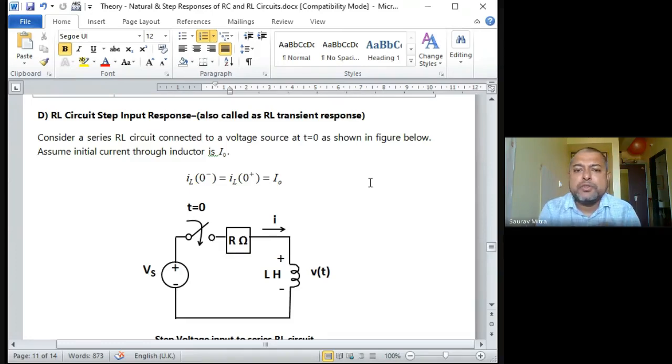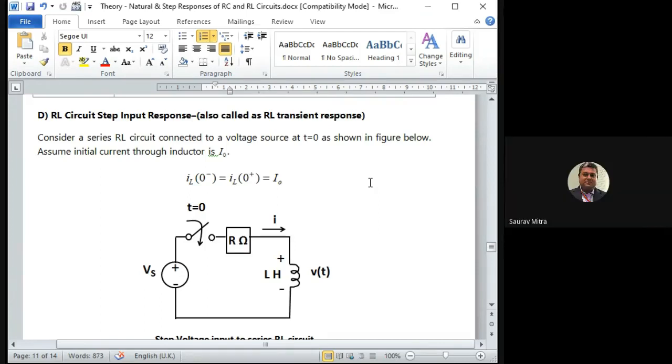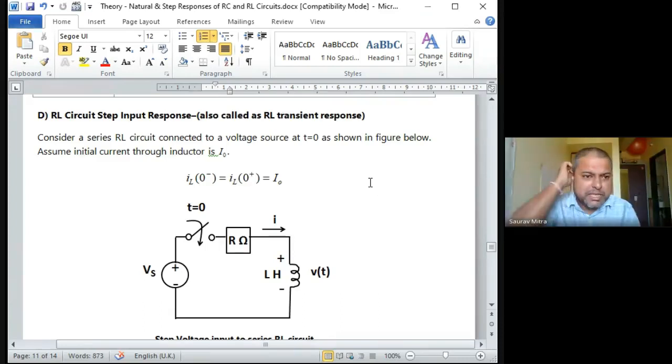So what is the conclusion we can draw from that last part of the experiment in experiment 2? That is the sampling theorem and aliasing effect and all those things. What we find is, if we keep a very high sampling frequency or sample rate, then we find very perfect reconstruction of the input at the output. So that part you keep as it is, you can study that. All the waveforms you check, just don't do it only for preparing the journal. Development of understanding is very much necessary. So that is what you do.